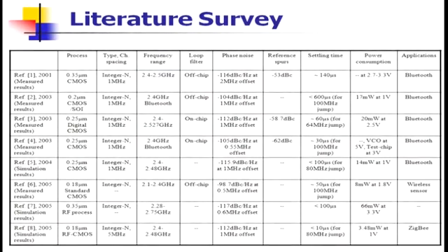In case of ZigBee, with the typical 16 channels, what does settling time mean? Your PLL is locked in say at the lower frequency 2.4, or at the higher frequency 2.48, and suddenly it goes back to 2.4. You are clear? So you are going from the left end of your frequency spectrum to the extreme right-hand end, 2.48, then you go back to 2.4.